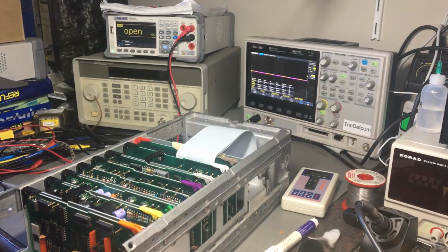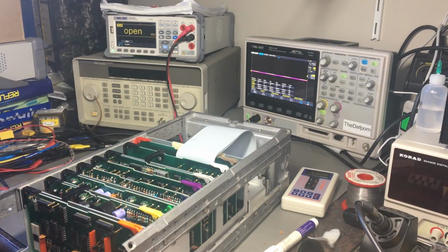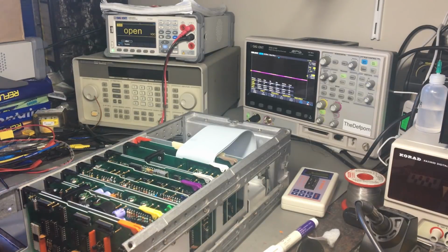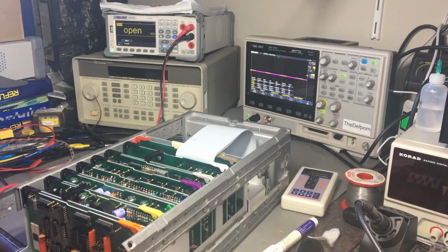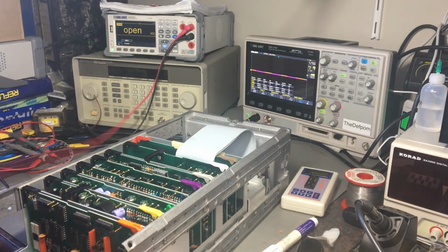Well, I decided rather than unsoldering these things, because they're just back-to-back diodes, I should be able to test them in circuit without taking them out. We'll see how we go. I've already got the meter set up for it. So let's have a look. Okay, 0.65, that looks right. Other way, same deal, that's good. That diode pair looks correct. Check that one. Yep, that's okay. So those diodes look fine. Doesn't appear to be that.